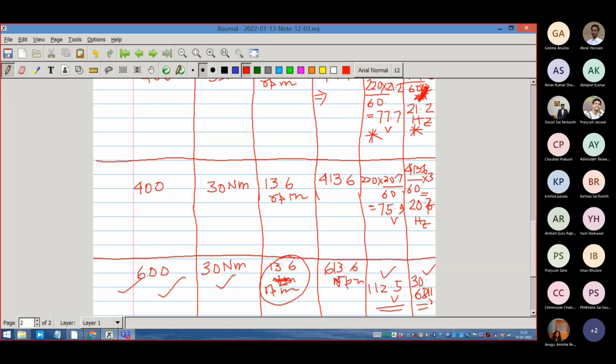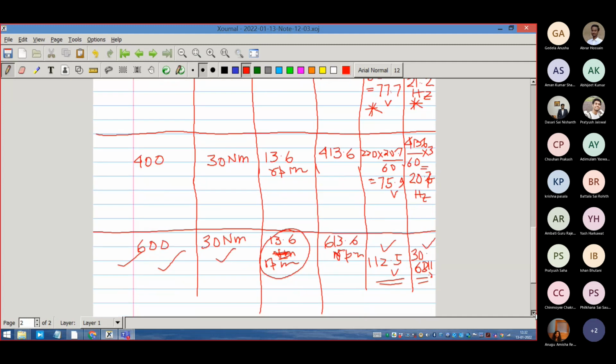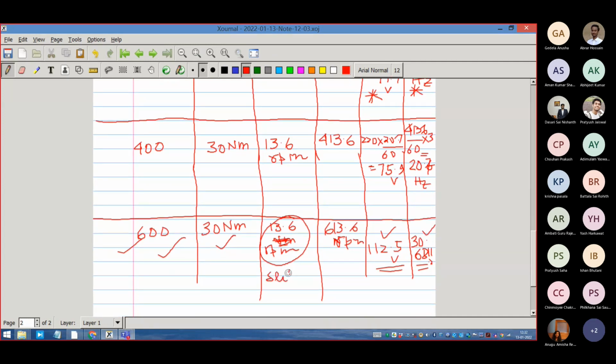We call it slip speed, or sometimes we give it a name. Slip speed we give s omega s. So until the error in the speed is 0, error in the speed meaning speed reference minus actual speed is 0, the slip speed will continue to vary through an integrator.